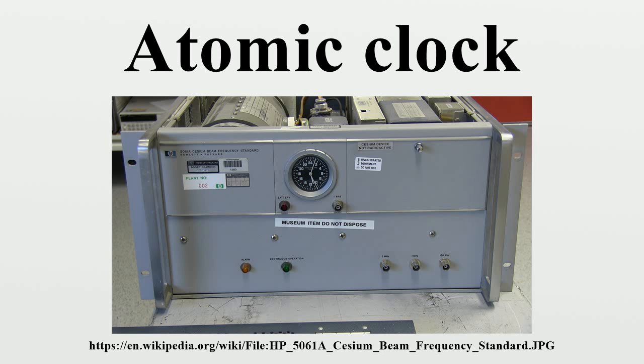The active maser is sensitive to wall shift and cavity pulling. The wall shift is mitigated by using PTFE coating to reduce the effect. The cavity pulling effect can be reduced by automatic cavity tuning. In addition, the magnetic field pulls the frequency. While not being as long-term stable as cesium beams, it remains one of the most stable sources available. The inherent pulling effect makes repeatability troublesome and does prohibit its use as being primary standard, but it makes an excellent secondary standard. It is used as low-noise flywheel standard for cesium beam standards.